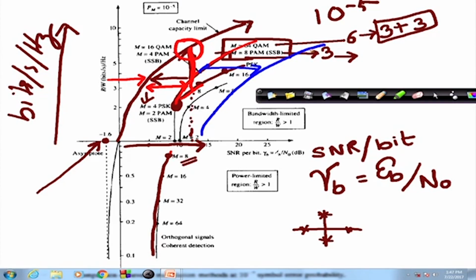And if we relax the error probability threshold, say we want to compare at 10 to the power of minus 3, it will be here. So, generally 10 to the power of minus 5 is a good number, and ideally speaking, during such comparisons, one should use error correction codes in order to compensate for the assumptions that have been made with the capacity expression.